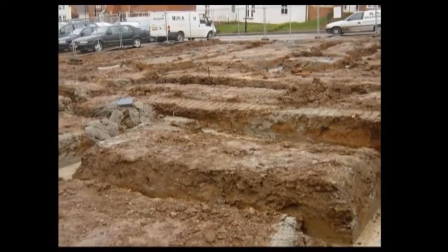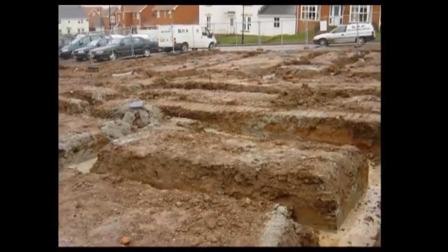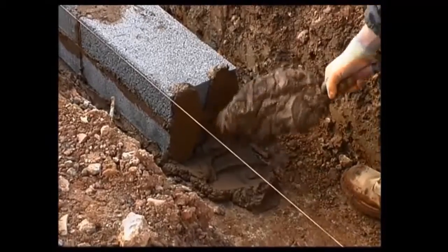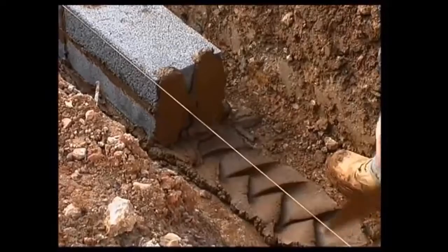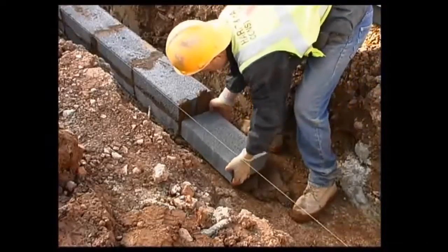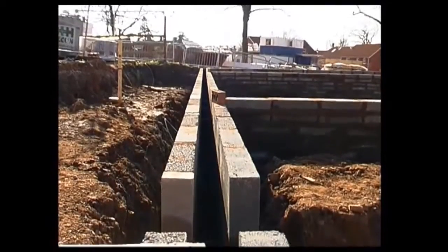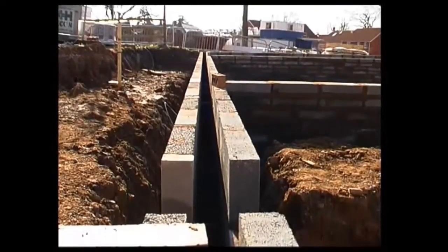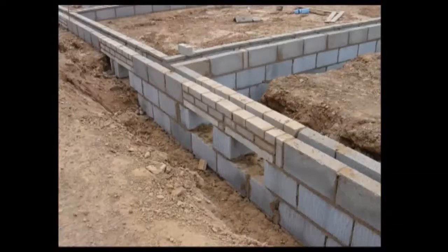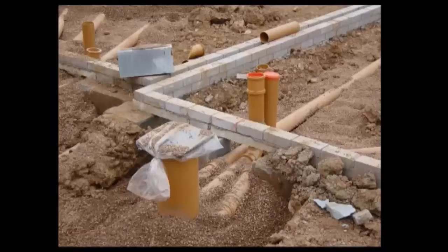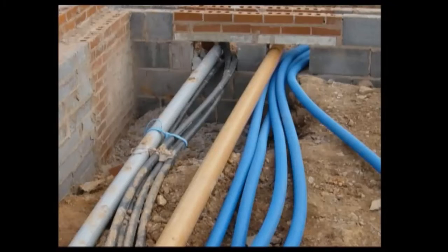Once the topsoil has been removed, the trenches dug and the foundations poured, the walls can be built to DPC level. Concrete blockwork is cheaper than brickwork and is much more likely to be used below ground level. It's normal to use cavity construction, although solid walls are equally acceptable. Before the floor construction can commence, it's important to lay and test any drains which run beneath the floor. Ducting can also be laid for other services such as water, which will be connected at a later date.